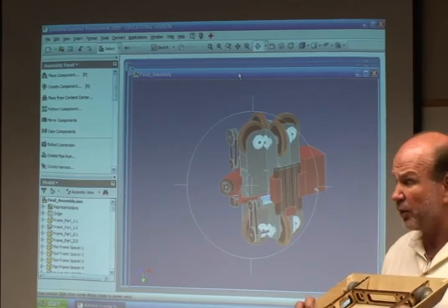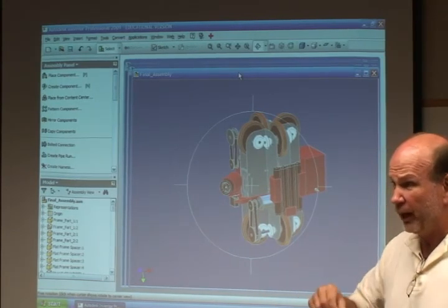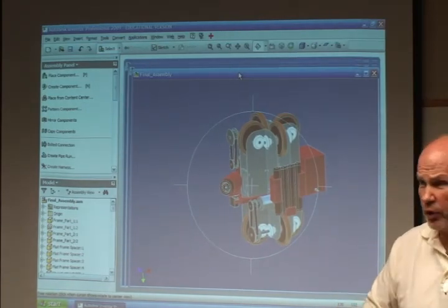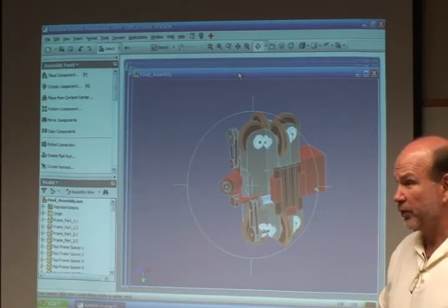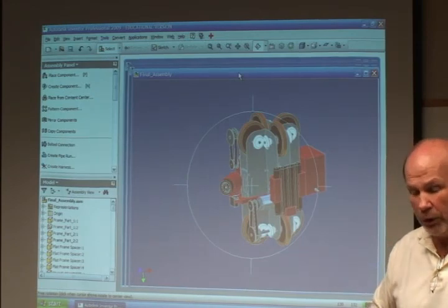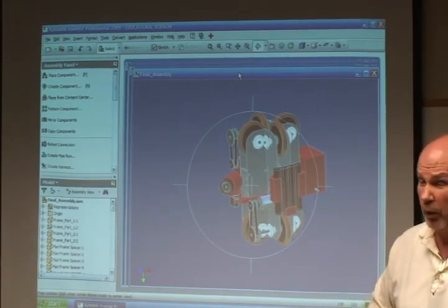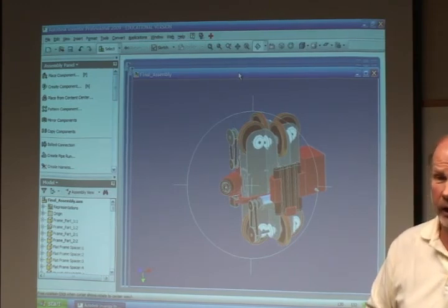Also, you need accessibility to any set screws that you have. Our first year with the original Shockwave, we were up against Jeff, and the set screw worked loose, and we didn't have access to it. We couldn't get to it in 15 minutes to tighten it up, so we had to go without a weapon. Well, that's the last time that ever happened.